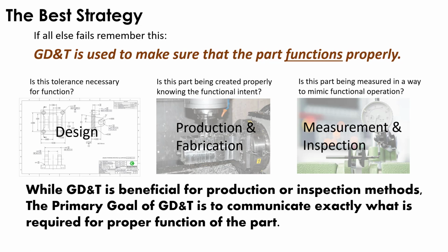So on this, just trying to conclude this here, Jamie, GD&T is used to make sure that the part functions properly. That's first and foremost. And like I said, coordinate dimensions don't convey that. Even just on simple shafts, stuff like that, it's not conveyed. When you look at two cylinders from a right side view that appear to be coaxial, well, how coaxial do they have to be? On a coordinate dimension print, there's nothing there to tell you that.